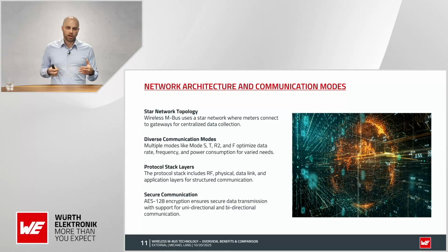All of them are based on different frequencies, as we also already heard before. Mainly in Europe, 868 megahertz is used as the sub-gigahertz ISM frequency band, because it's free of charge and you can use it in industrial, scientific and medical applications as SRD bands, and so again it is very cost effective.